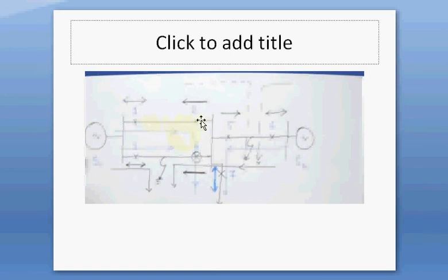Now after the occurrence of the fault, the current is from left to right, so the direction of current is reversed. Therefore we need to place a directional relay at position 5, and it will operate for the direction indicated by the arrow above. So clear? Now we will see which type of relay we need to put at